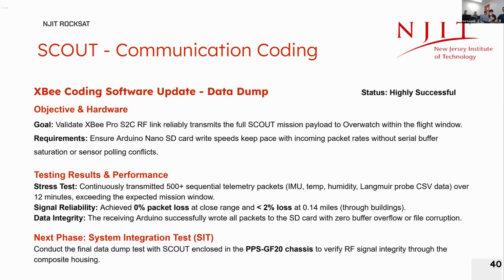And then data integrity: the receiving Arduino successfully wrote all packets to the SD card with zero buffer overflow or file corruption. Next stages would be to conduct the final data dump test with Scout enclosed in the PPS to verify the RF signal integrity through the composite housing.